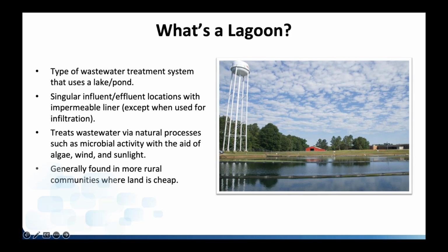The lagoon is relying upon microbial activity within it, with the aid of algae, wind, and sunlight, to break down the waste. They do take up a decent amount of space, and that's why they more generally are found in more rural communities.